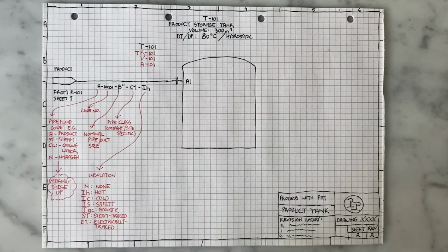The reason I mention this is that while I don't need to show every flange on every single pipeline, nor do I need to show things like bends for that matter, I usually do show the flange that attaches a pipeline to a nozzle on a tank.